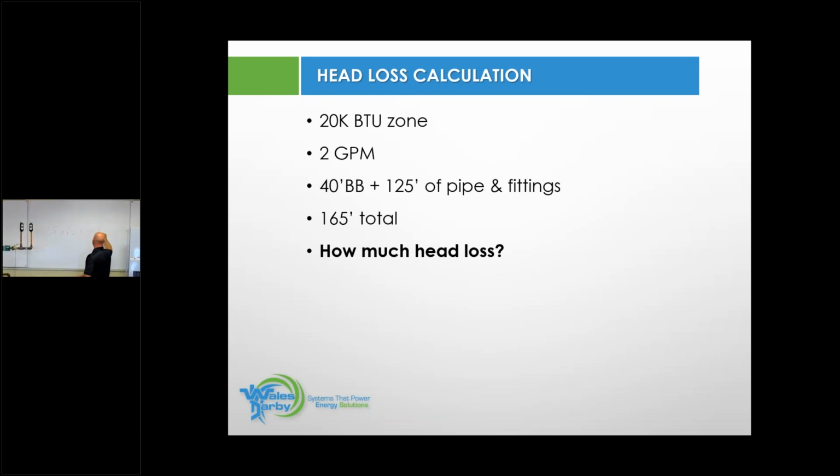And that's going to equal 9.9 feet of head. So the 0.04, that's looking at our flow rates, velocities through that pipe, and we come up with 9.9 feet of head. Is everyone comfortable doing that? Because this is going to be a theme of what we're going to be doing here going forward.